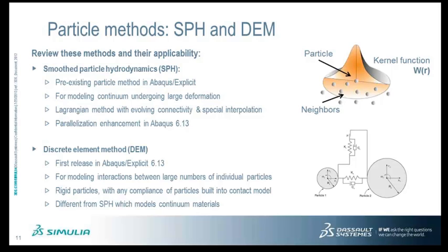And DEM is actually for modeling interaction between what you typically think of as particles, sand, granular particles. And these particles only interact with each other through contact. You can see that in the schematic on the lower right-hand corner. We have two particles, and you can see that they just have springs and damping between them, whereas the SPH up top actually interacts through the constitutive law.